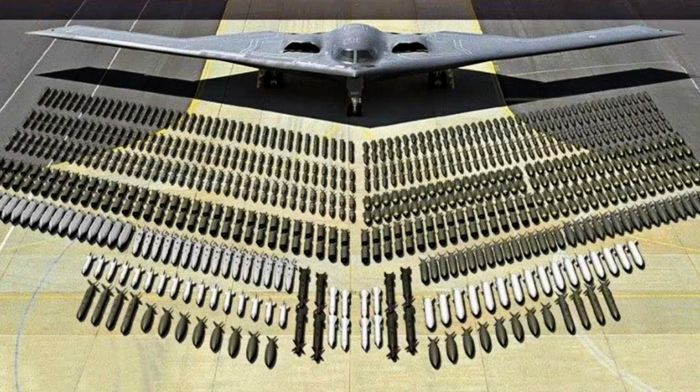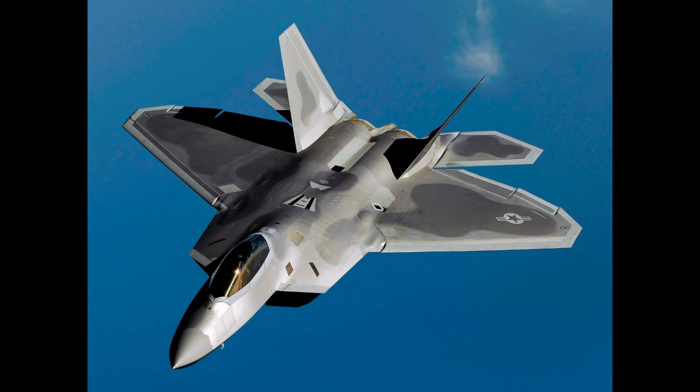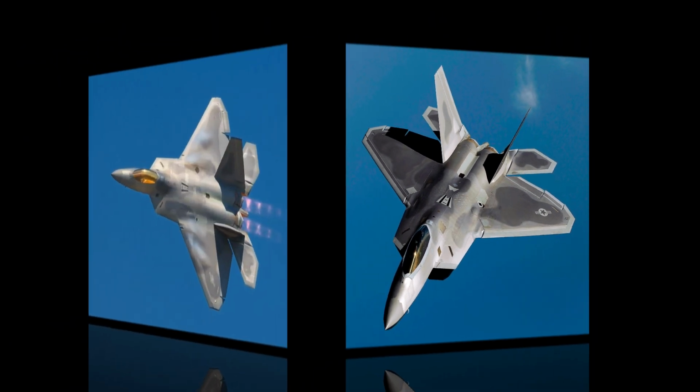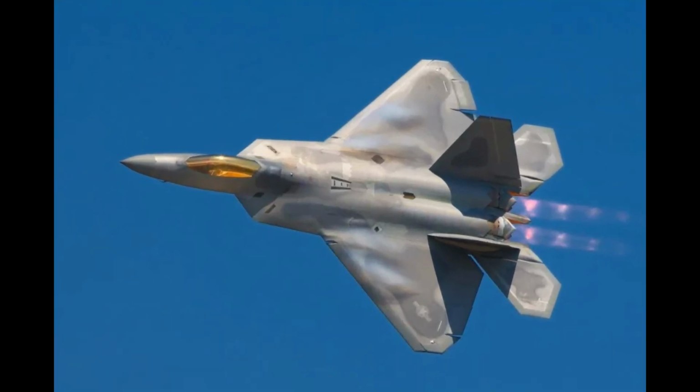Lack of corrosion is a third advantage of composites. Boeing is designing the 787, with its all-composite fuselage, to have both a higher pressure differential and higher humidity in the cabin than previous airliners. Engineers are no longer as concerned about corrosion from moisture condensation on the hidden areas of the fuselage skins, such as behind insulation blankets. This should lead to lower long-term maintenance costs for the airlines.